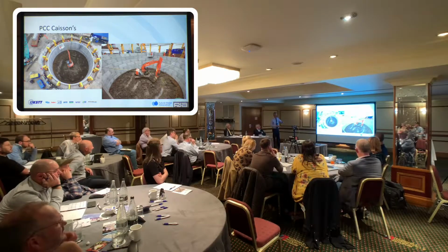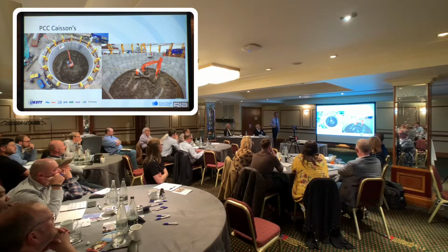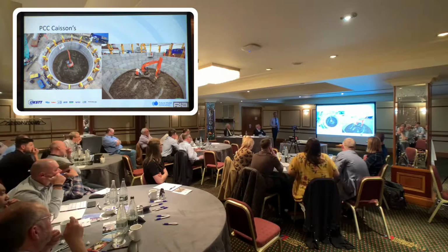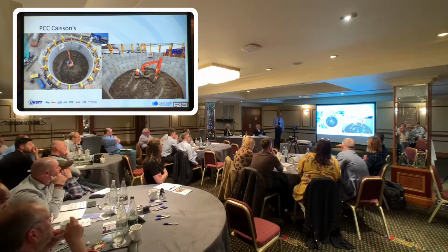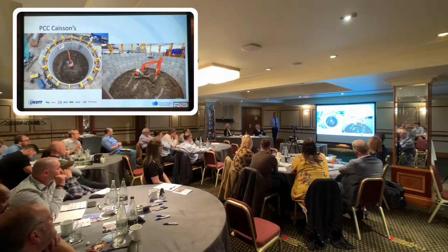There are now options to have bolts on the back of the shafts, which is a much safer solution. But it's not to say that this isn't valid. We're actually doing a project at the moment in Barrow-in-Furness. I can't really tell you where it is, but we're sinking some caissons over magnetic anomalies that fell out of the sky in 1940-something. And we're using internally bolted rings because we may need to actually remove the bolts after we've finished the shafts.